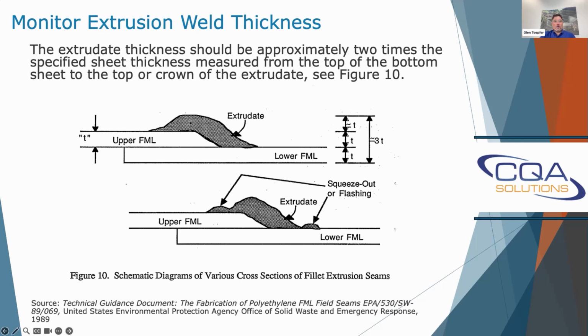And you'll see that in cold weather or cooler conditions, a lot of times you get installers and they're lumping it up. They're making a high weld. And there are different studies that seem to be showing that that's not a good idea. That's resulting in the weld cooling at different rates and resulting in crystallization of the weld and a weak weld ultimately.